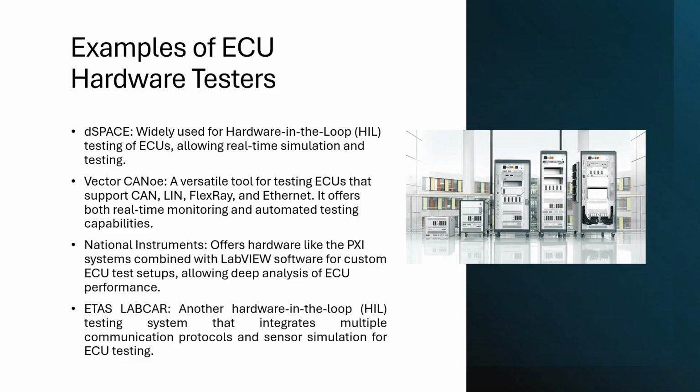Vector CANoe is another versatile tool for testing ECUs that support CAN, LIN, FlexRay, and Ethernet protocols. It offers both real-time monitoring and automated testing capability by means of software scripts.